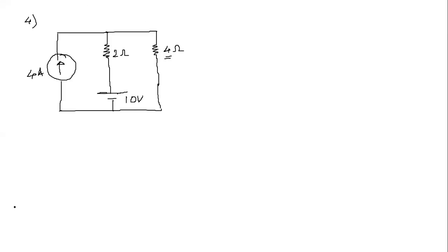So how do I solve this one? In this circuit, I have a current source, so I cannot use the KVL. Let us write down the nodes, A, B, C, D, E, F. I cannot use KVL for this junction, neither can I use it for this outer loop because it involves this branch where the current source is. Now, how do I solve this? I'm left with only this loop.